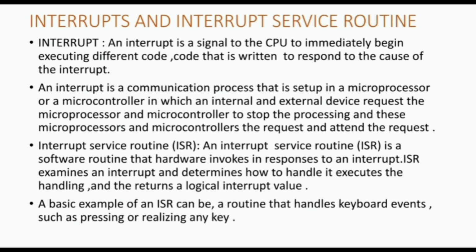And now the interrupts and interrupt service routine. What is an interrupt? An interrupt is a signal to the CPU to immediately begin executing different code that is written to respond to the cause of the interrupt. An interrupt is a communication process that is set up in a microprocessor or a microcontroller in which an internal or external device requests the microprocessor or microcontroller to stop the processing, and the microcontroller accepts and attends to the request.